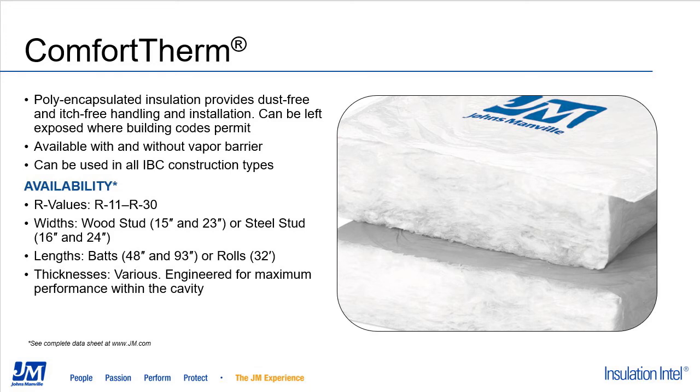The encapsulated facing provides a barrier between the fiberglass and the installer that limits the itch effect that fiberglass tends to have. I do want to point out that the ends of the bat or rolls are exposed, but the product may be left exposed except in applications where UV exposure is possible. This product is fire rated and can also be used in all construction types. The facing is a vapor barrier, but we do have options for non-vapor barrier facings.